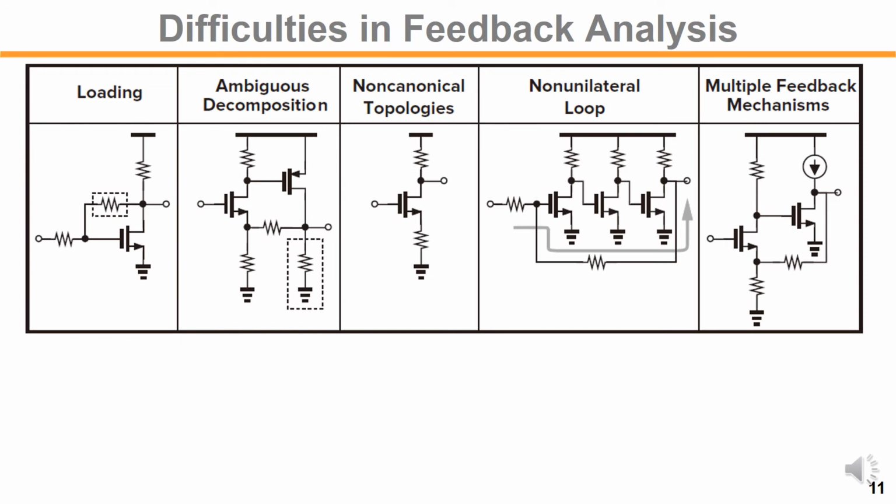As you may have noticed, there are many different topologies. In our feedback analysis, we were simplifying everything like feed forward gain A and feedback factor, feedback gain beta, and plus and minus at the input, a subtractor there, something like this. So every signal had a quantity. We just multiply the quantity and subtract the quantity. The amplifier output will be A times x minus beta y.